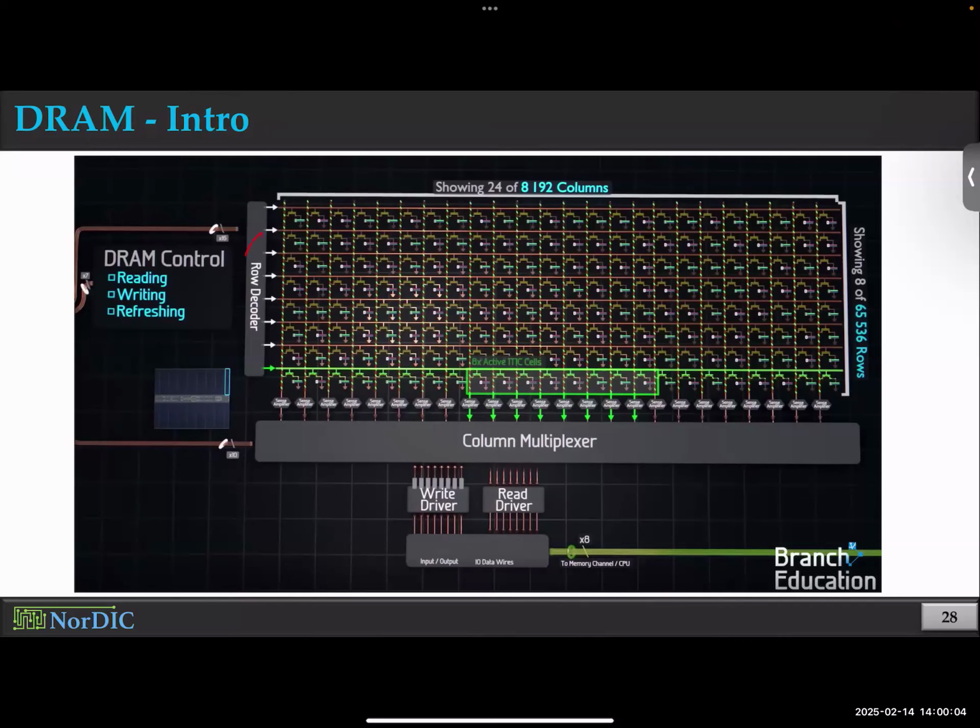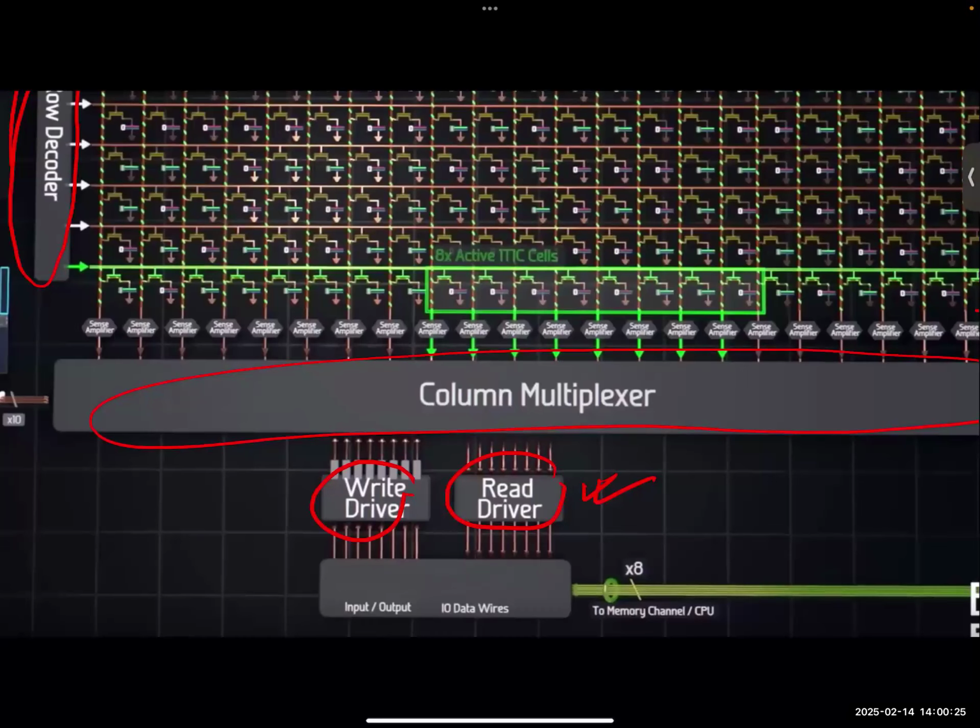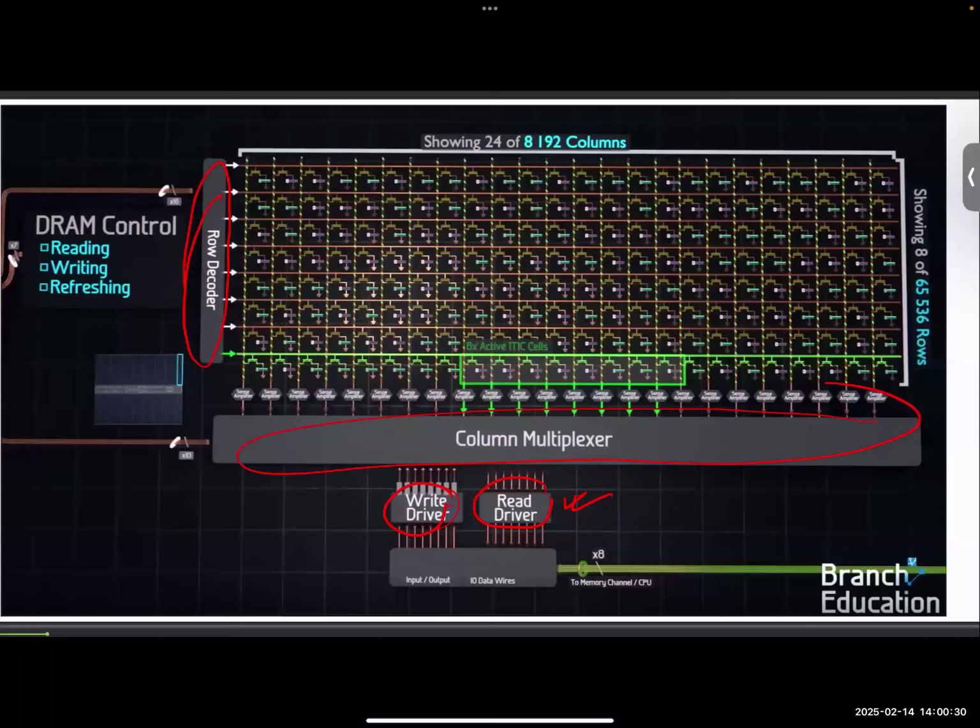We definitely talked about the fact that you have row decoders, and column multiplexers or column decoders, didn't we? We had a very general discussion towards the very beginning of this course anyway. This is just showing you how the realistic picture looks. And then you have some write driver, read driver. The read driver provides the biasing levels for the read operation, and the write driver, as you can imagine, for the write operation. And as I said, we will discuss this soon enough.